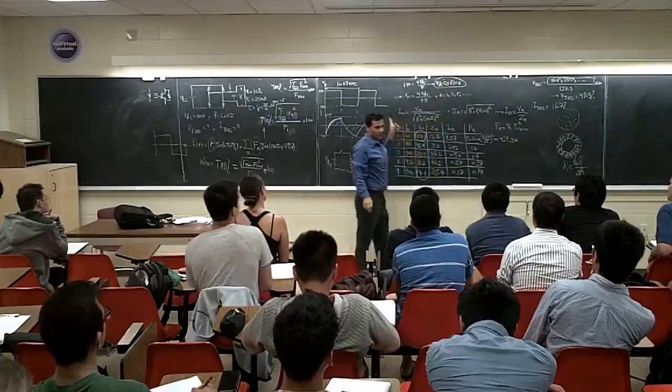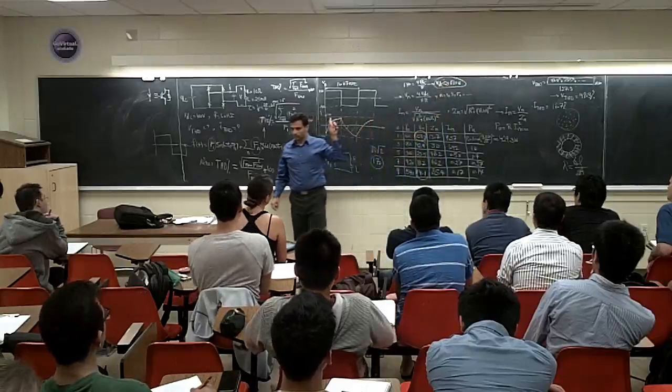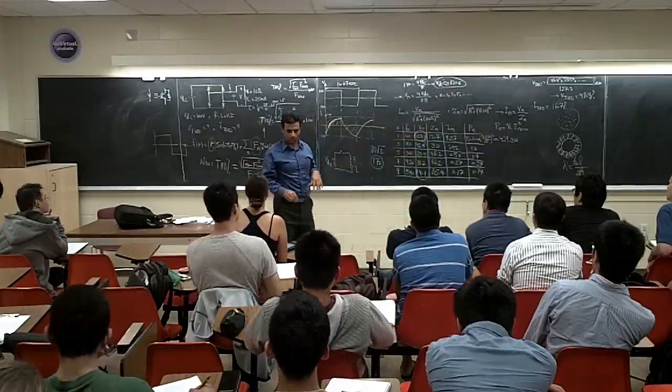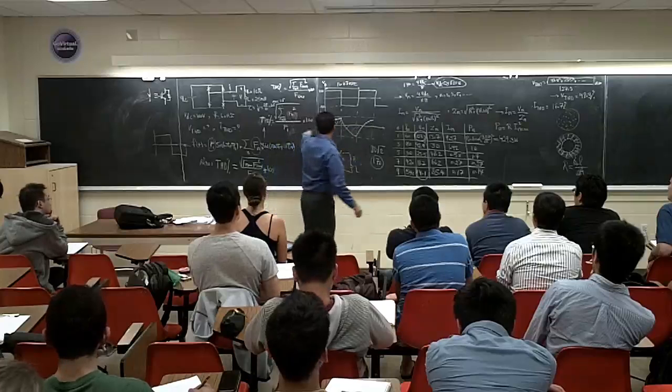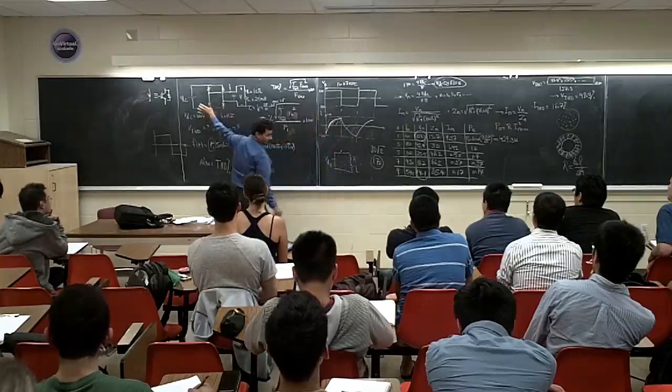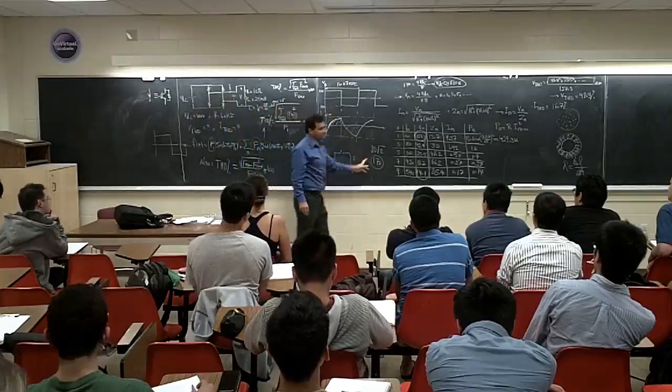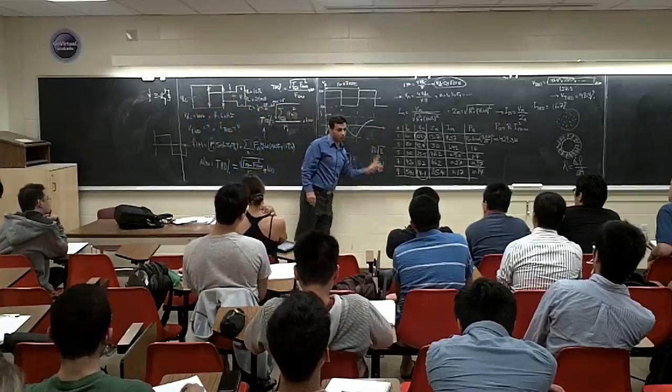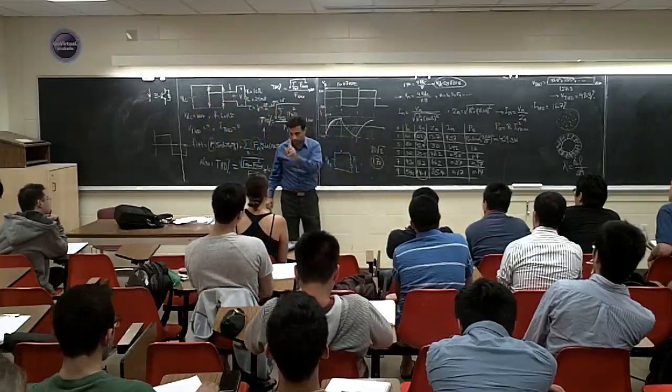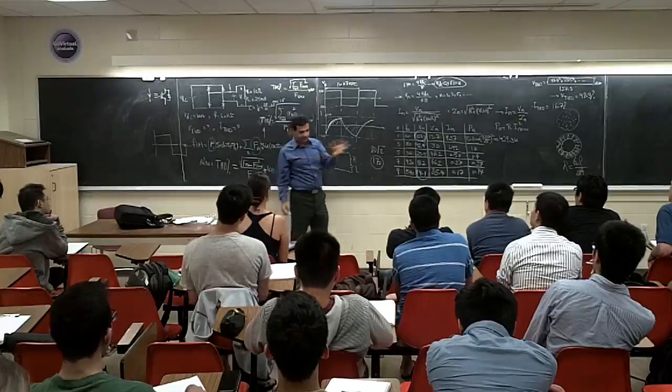Right? If you want to design this inverter for home, you want to build a little UPS at home, you should make sure you have at least a 130 volt battery here, to be able to get how much? 110 volt for the first harmonics. For the first harmonics, keep in mind, this is a simple design.